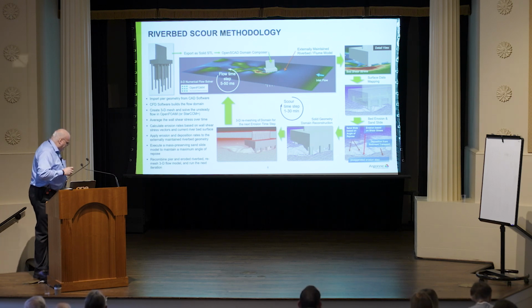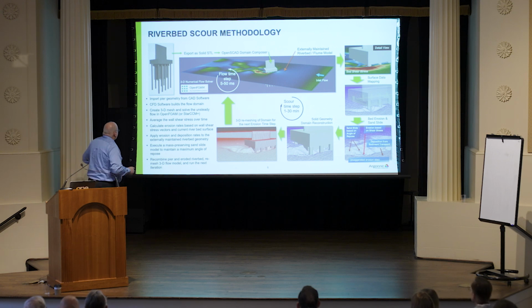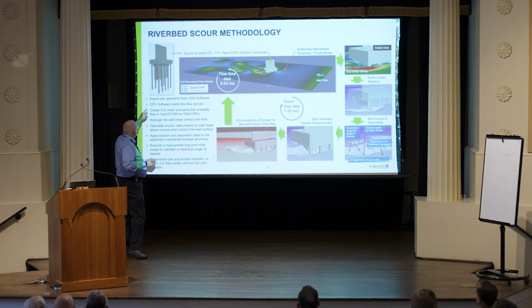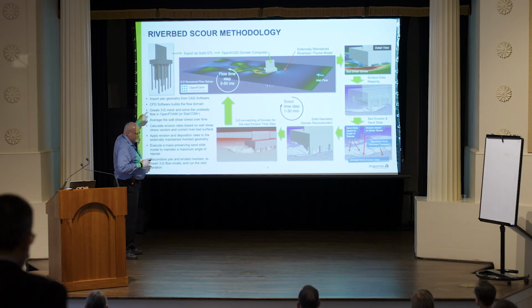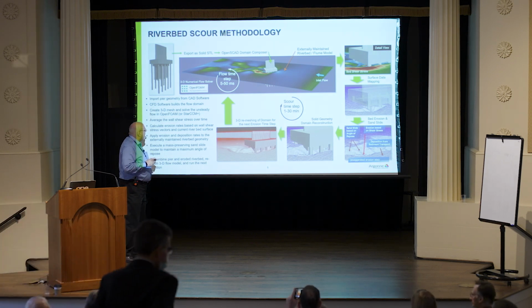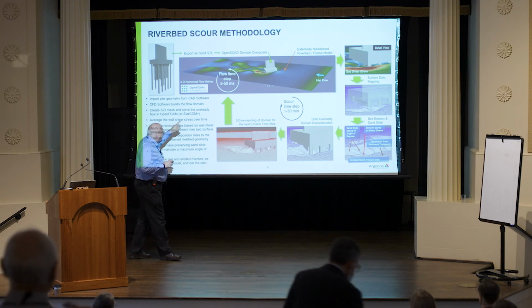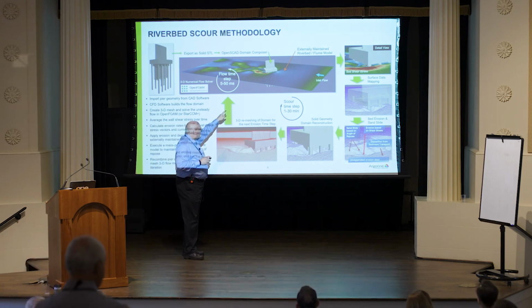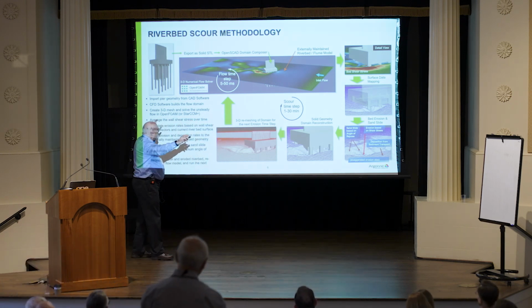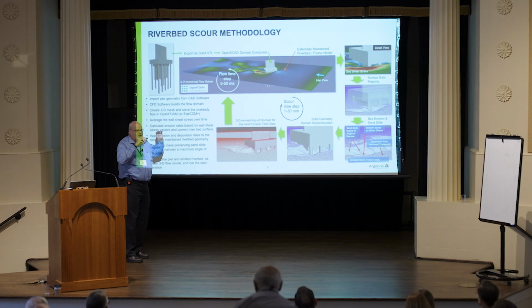So we can deal with very, very complex bridge structures, right? So you see here the Pier 22 from the Feather River Bridge that is redesigned and has an extremely complex shape. Lots of H-piles in the center, the cylindrical piles around, right? So what we do is we embed that into a three-dimensional model, right? That's just the long bar at the top. And of course, I'm not showing the water level, right?